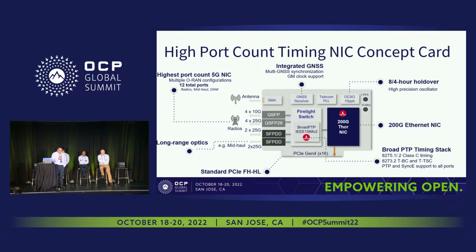It has obviously timestamping on every port, and it has an embedded CPU sitting next to it. And the second independent node is the host CPU, the server, together with the NIC having its own independent timestamping capabilities. So if you think about how you can allocate synchronization functionality to this architecture, there are many possibilities, and this block diagram, this architecture provides you with significant amounts of flexibility in the way that you